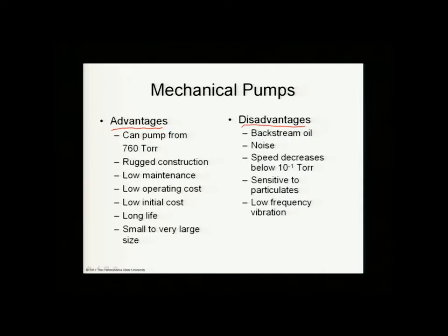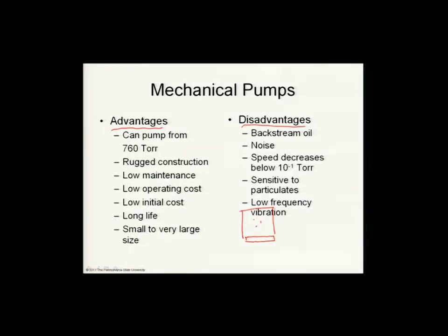And by the way, in one of the earlier lectures I mentioned a very simple use of vacuum pumps that has nothing to do with creating processing environments. Here's a processing environment, where we're doing all the work to control the molecules. But another use of vacuum pumps is to take a block like this and put holes in it, as we talked about before, and then have a vacuum pump down here that's pulling on this so that you can hold a sample here.